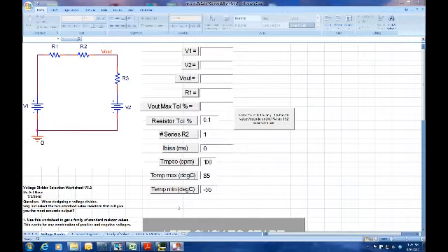So what we're going to do here is have a voltage divider, and it may look a little funny at first, but bear with me. We have V1, V2 feeding 3 resistors. The main purpose of this is to design some voltage dividers for power supplies where you're going to put a small amount of resistor over here in R1 so you can do control loop testing. However, for a standard voltage divider, R1 is going to be equal to 0, and then V2 will probably be 0, and V1 is going to be our normal input voltage. So let's see how this works.